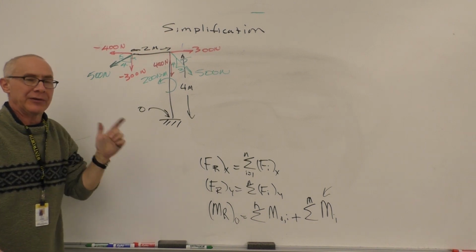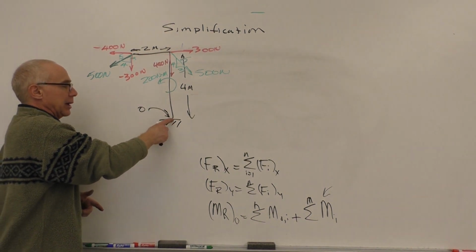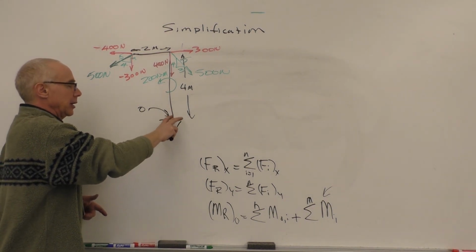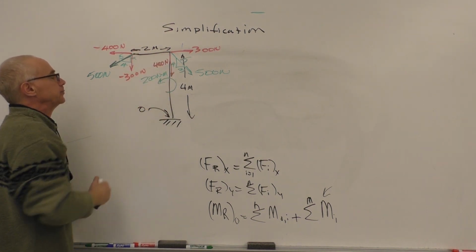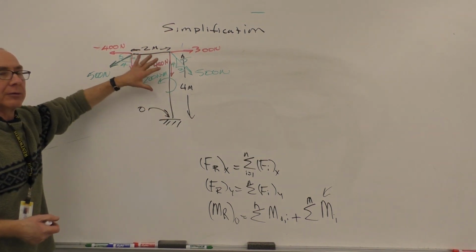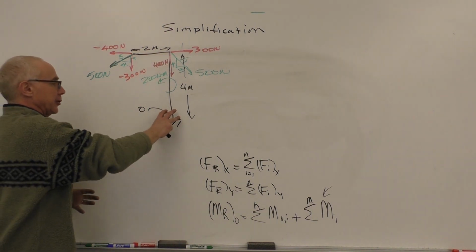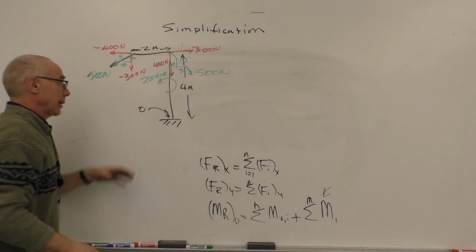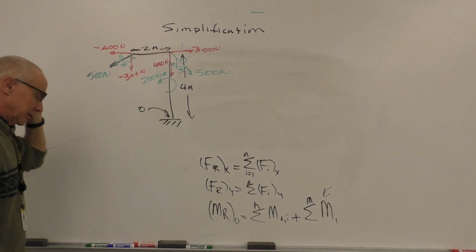But from the standpoint of external forces, the support, what's happening down here, it's okay. We can just put the force down here and the moment down here, and that'll be equivalent to this complicated system from the perspective of these external supports that, remember, can't see what's going on up there. Remember, it's a rigid body, meaning there is no deformation.